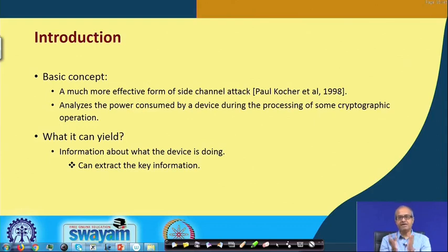The idea is that in timing analysis attack we are measuring the time, right. Here we are trying to measure the power that is consumed by the device. Suppose there is a battery operated device that is working, inside some cryptographic operation is going on, maybe a smart card reader, let us say. Somehow I am measuring how much current that device is drawing from the battery or from the power supply source.